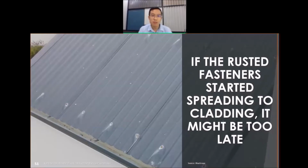So in the longer term, if the fasteners fail and start rusting on the crown, there is still a chance for you to salvage it by replacing the fasteners, until a point where the fasteners have started affecting the cladding around where it is in contact. Then, based on our experience, it's very hard to remove all these white stains, and it's not really a permanent way to solve it.